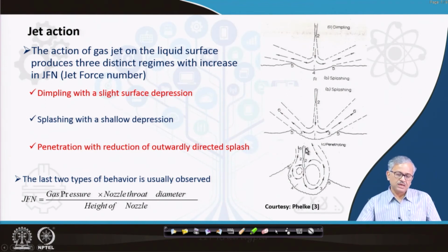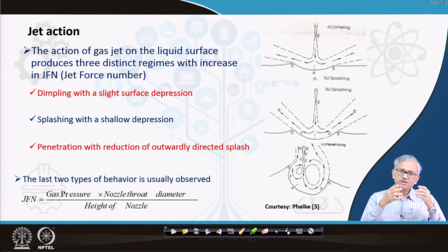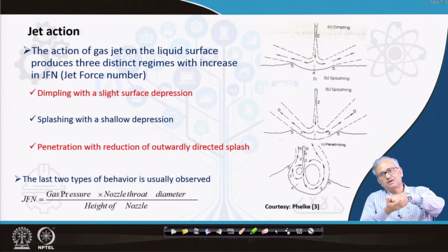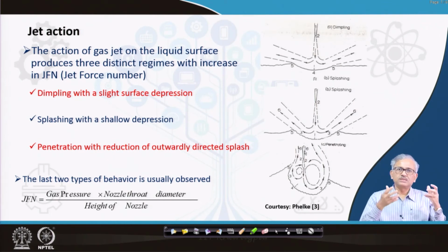And the second thing is that, depending on the GFN, you can produce the big carrier, small carrier also. And depending on the GFN, two parameters are there. One, if you increase the GFN, your rate of decarburization also increases. Why does it increase? Because when the GFN increases, your partial pressure of oxygen is increasing, because you are giving more pressure on the liquid surface. So the oxygen partial pressure becomes more, and as a result, your decarburization rate also becomes high.